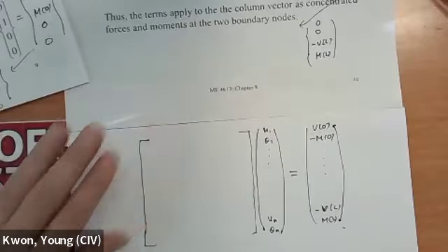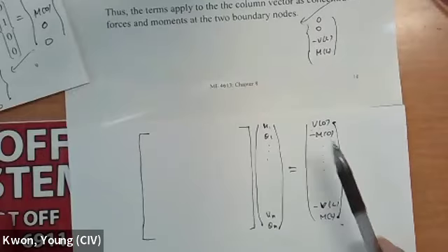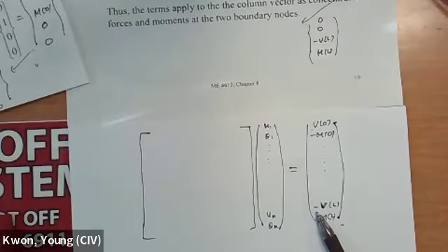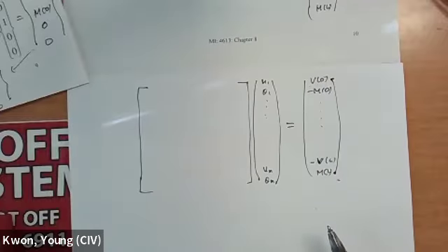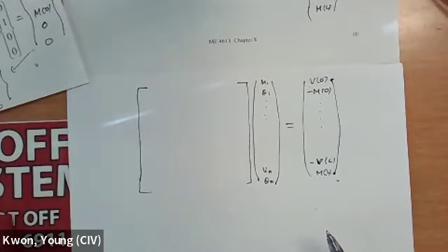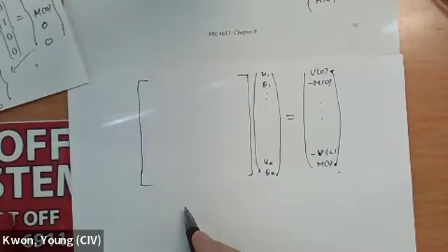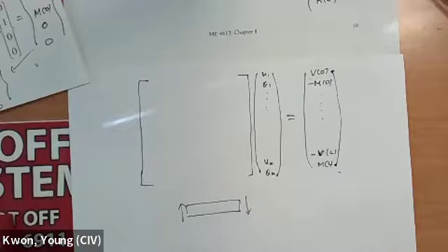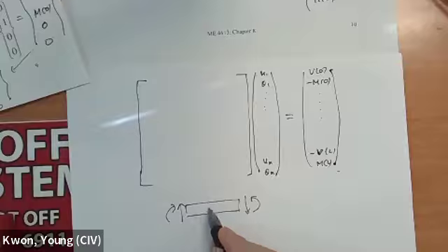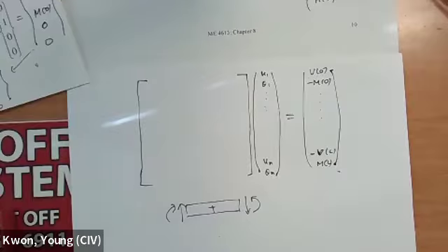Then you see that these signs are a little bit confusing to remember, the negative moment and negative shear force in here. The bottom line is, no, you don't have to worry about that. The reason is the following. When we developed the beam bending equation, that was the positive shear force and that was the positive moment in our sign convention.